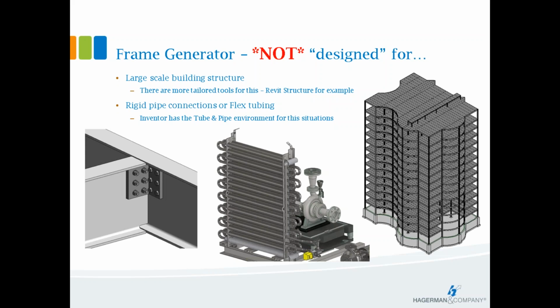Same situation applies here. If your job is doing large-scale structural framing, there are other tools that are more tailor-made for that. Inventor can do it, but it will end up taking you longer in Inventor as opposed to the other two tools such as Revit Structure. So a large-scale building structure, you don't want to tackle it with that.